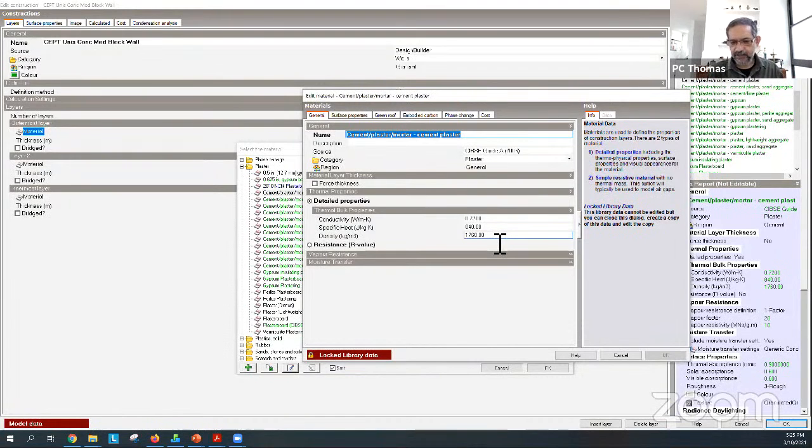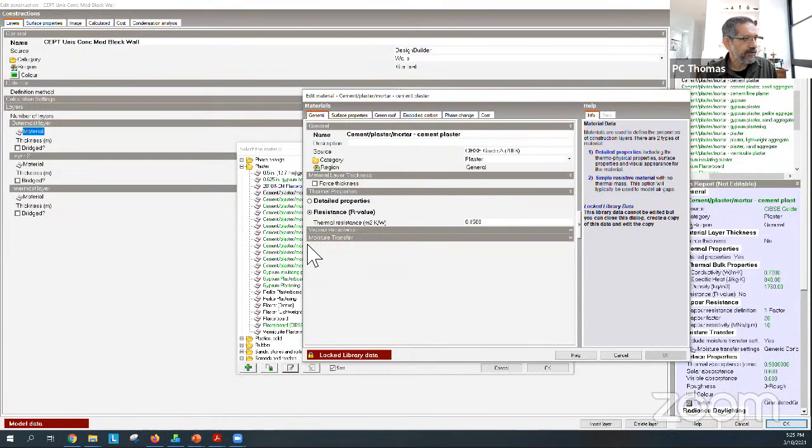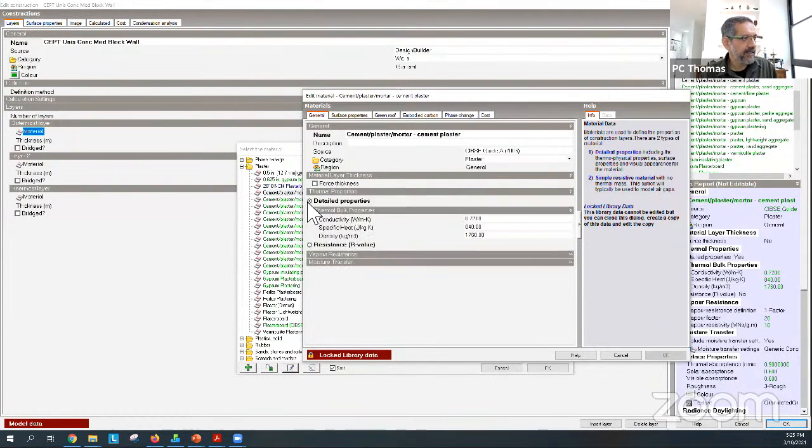and that allows the model to calculate this dynamic nature of the building fabric storing and releasing heat. Within all these energy simulation models, there's at least 7 or 8 hours of history of how heat was stored by this from the sun or from external ambient temperature within the building fabric, and then as the temperatures cool during the nighttime, how that heat is released and where it is released to. So it's quite important to give these detailed properties, okay? You can give a simplified R value, but an R value completely negates the thermal mass impacts.